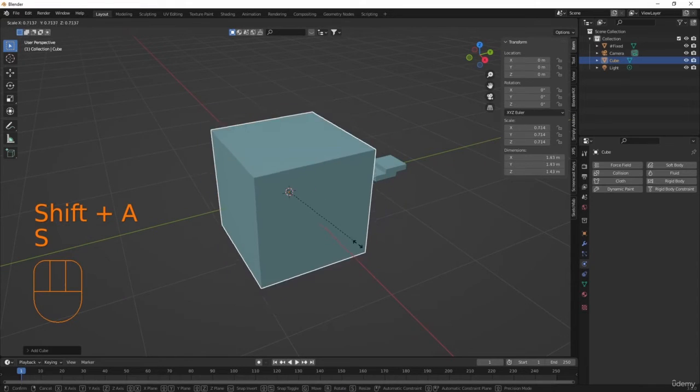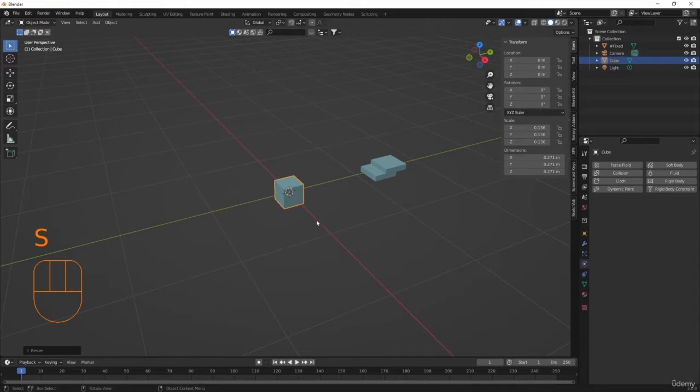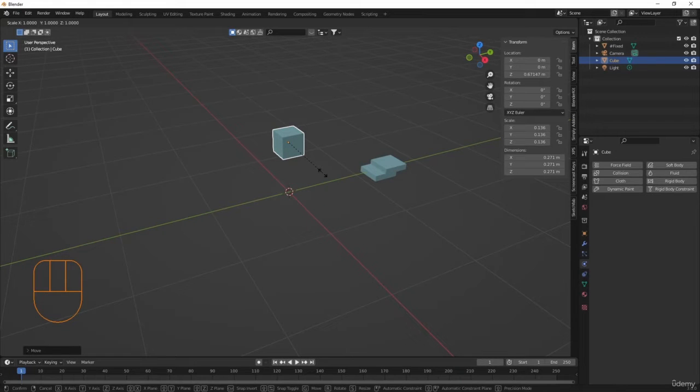And we're going to actually use this rigid body quite a bit. So we're going to ultimately be designing suspension systems. And typically on a vehicle, on each axle, you have a suspension system, and each suspension system will a lot of times have a subframe. We're actually going to use the subframe later. So let's make a subframe, and it's going to act as the controller for each axle that we make. And this will be obvious throughout the course.